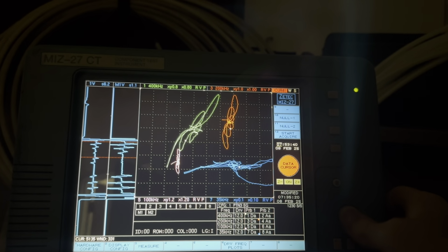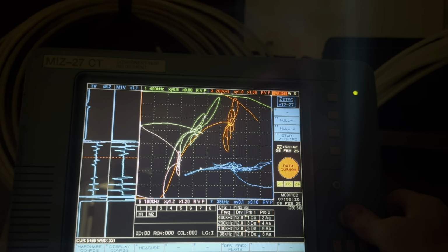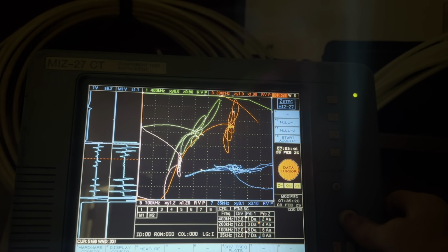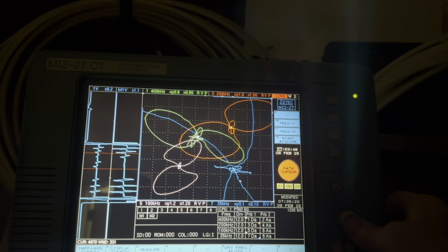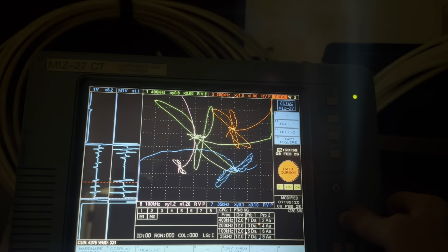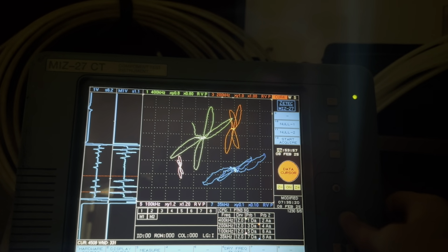Yeah, we've got some of those signals at the other end of the standard are actually wear scars, so they're a bit wider. Then you have a non-flawed TSP right there on all the channels. And then I go a little bit further below. That's when you get the Cal standard flaws